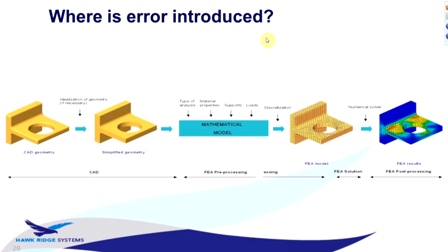If you see error between the results you're getting and what you would expect from, let's say, a hand calculation or real-world result, it's typically related to differences in the geometry, whether you've maybe modeled it differently than the real model looks like, or perhaps if you simplified the geometry in a way that also removed some detail that you needed. And of course, meshing can also introduce error, and that's the whole point of convergence, to try to get that part of the error out of the equation.